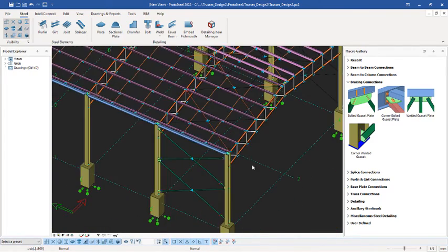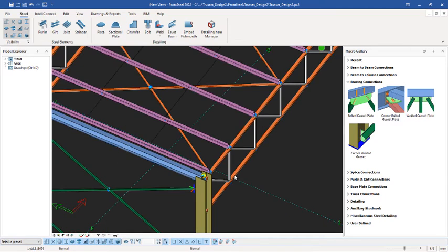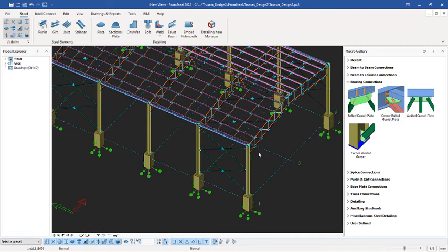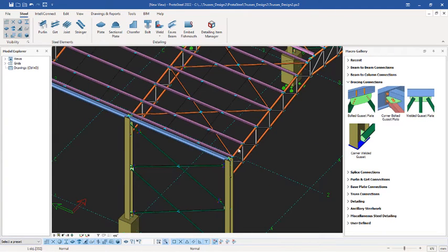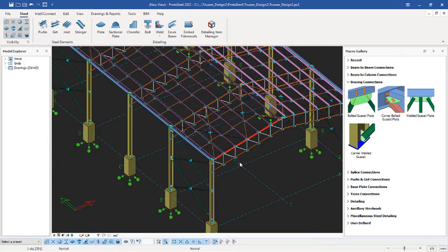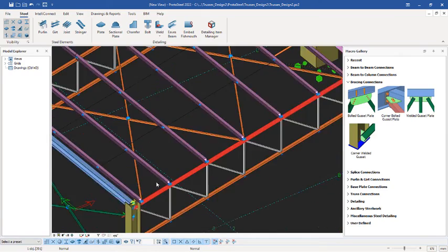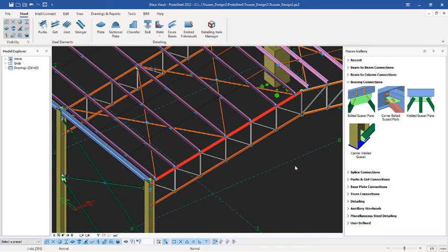So having understood that, let's move to the purlin connections. Sometimes there is an option we call interlink connect. In a small structure like this, I would advise you shouldn't use interlink connect. You should just connect them one by one so that you can have neat connections. Alright, so for the purlin connections, you can actually navigate to where you have the purlin and get here.